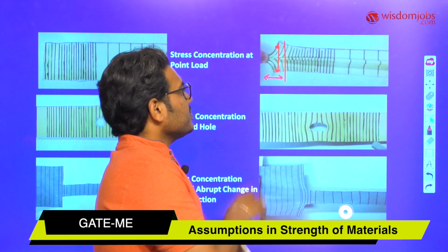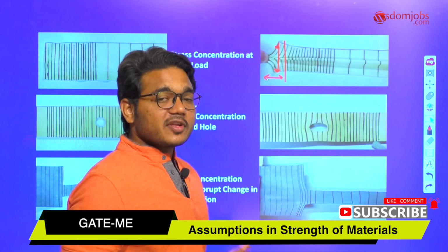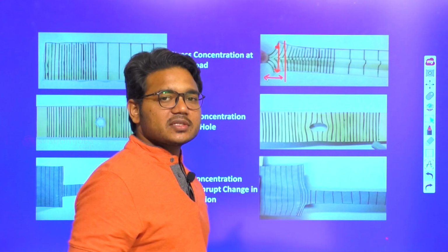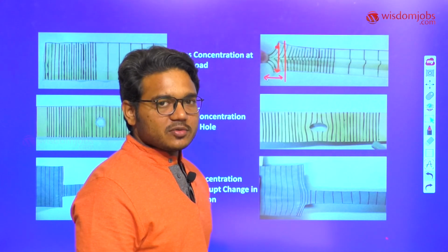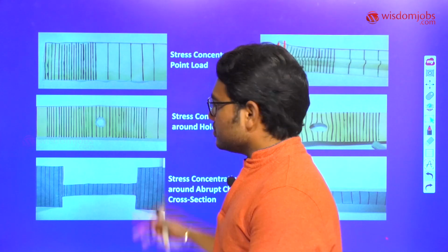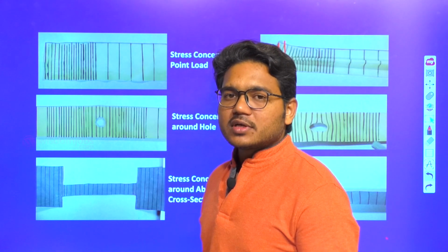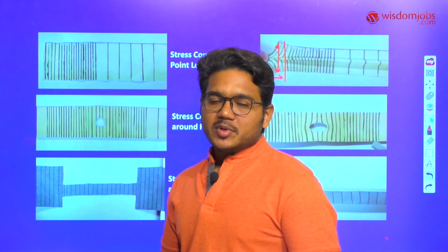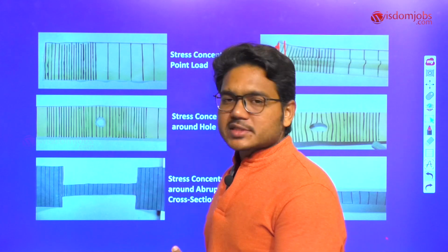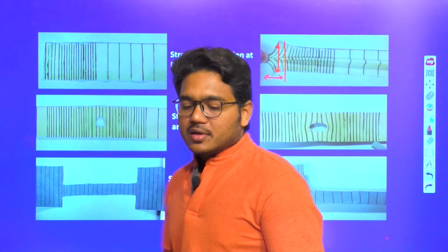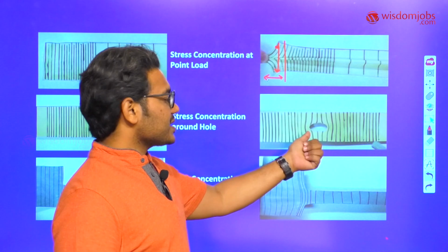That is, the effect of the nature of the load is only till a certain length, beyond which the analysis can be applied, that is, the stress can be considered uniformly distributed. So that is Saint-Venant's principle. And by extension it can be applied to other cases where you have sudden changes or sudden discontinuities in the material. The hole is a discontinuity here, and an abrupt change in the cross section is a discontinuity here. We will see the behavior of the deformation in these pictures.